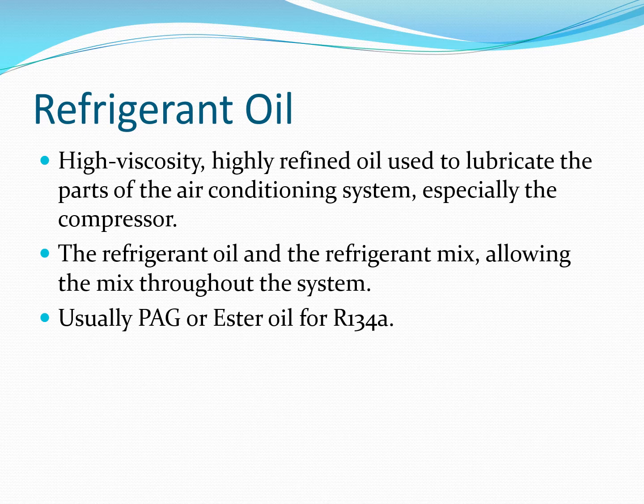They do not mix well if you're mixing them. So if it requires ester oil, put ester oil in it. If it requires PAG oil, then you need to put PAG oil in it. Our R12 systems used mineral oil and mineral-based oil. So if you are converting, say, an old vintage car, a pre-1994 vehicle of some type, to 134A, then you need to make sure that you're getting all of that old mineral oil out and that you are putting in either ester oil or PAG oil.